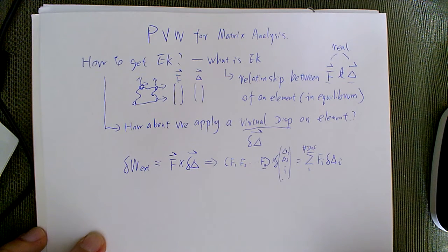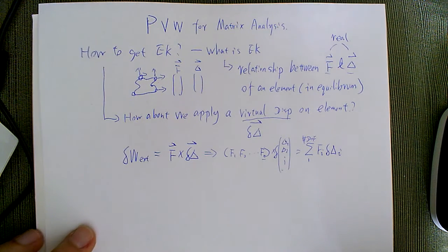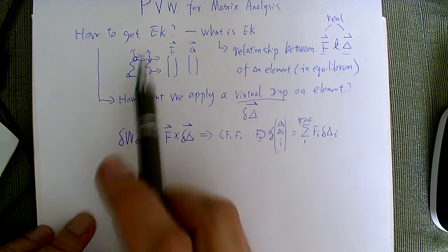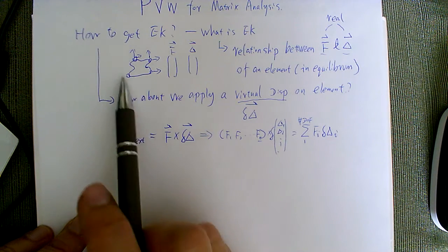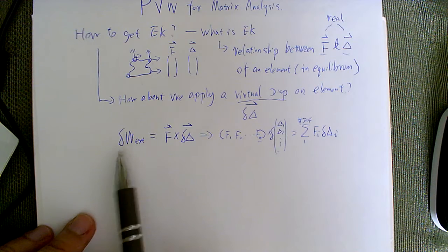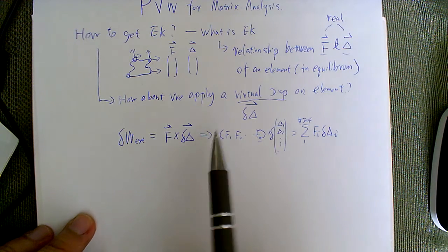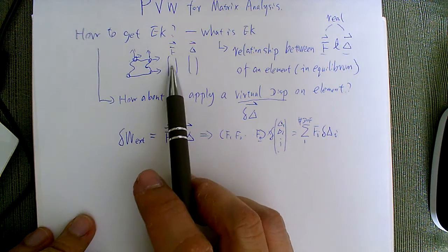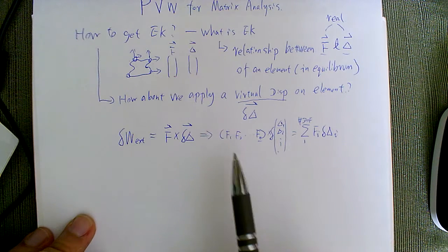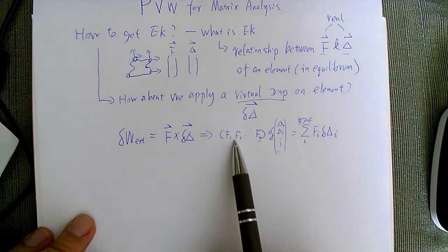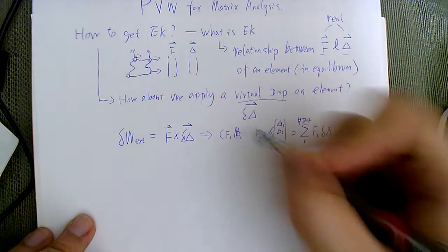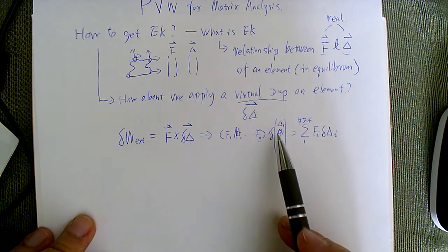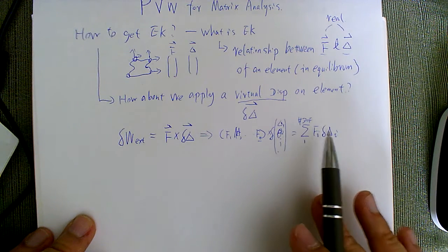Okay, that's all cool. If you define a degree of freedom of an element, you can just write this, no problem. Then you're like, oh, okay, how about the beams? We have rotation and moment. It's the same, because if there's a moment M here, then your delta here will be theta. Then the moment does work on rotation. So yes, it still works.